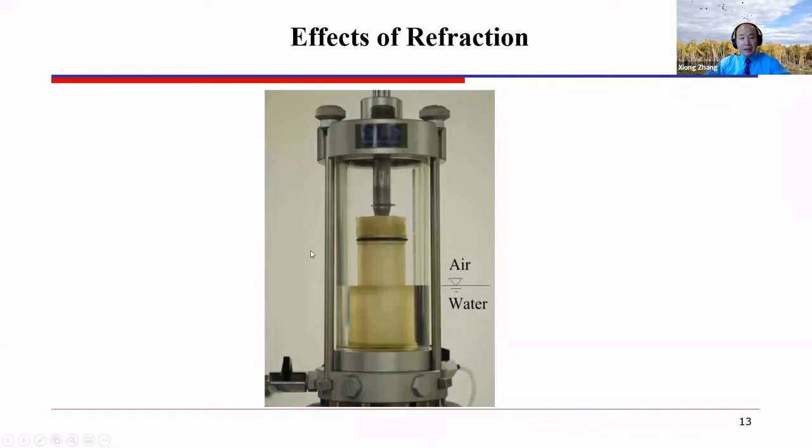So I asked my student to half fill the triaxial cell with water, and as you can see, with or without water, due to the effect of refraction, the soil specimen has been distorted significantly. So if you do not consider the refraction effect, your measurements cannot be accurate.